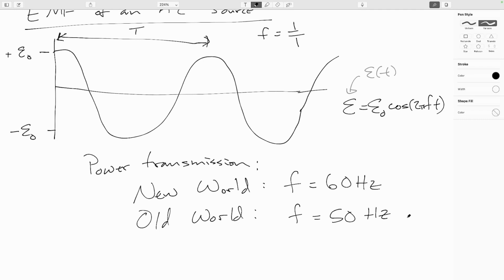But for pretty much anything else, most computers, things like this, they have automatic switching power supplies at this point, so usually all you need is just an adapter that changes the shape of the plug from where your computer was meant to be used to where it's going to be used, and the power supply in the computer will just automatically measure the voltage, measure the frequency, and then configure itself to work with that, since it's just providing DC to run the computer anyway.